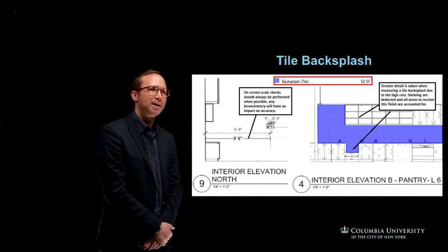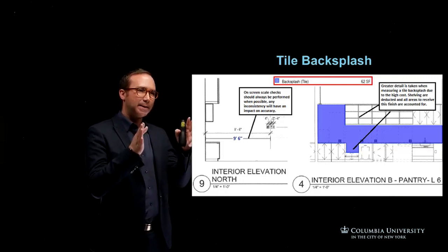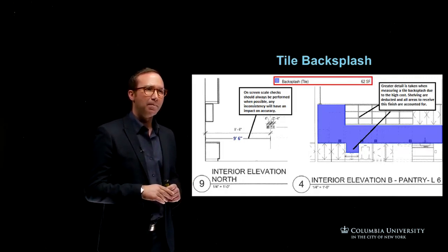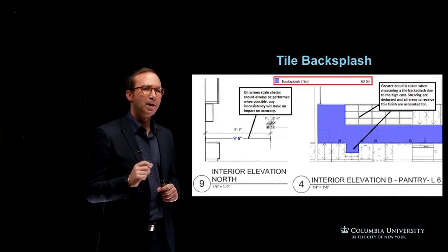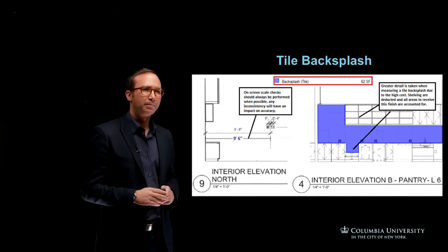Again, if you're doing it manually by hand with a scale rule, you would really just split that area up there in blue into different squares and oblongs. Keep it as simple as possible, and you'll get to that measurement there of 62 square feet. So just remember the way you record this, the description of it, the location of it is really important as you're doing your measurement.